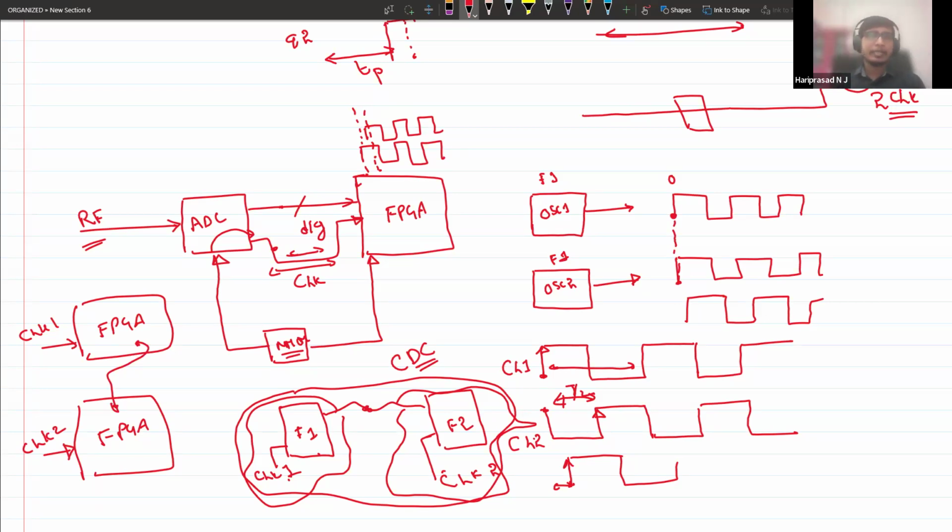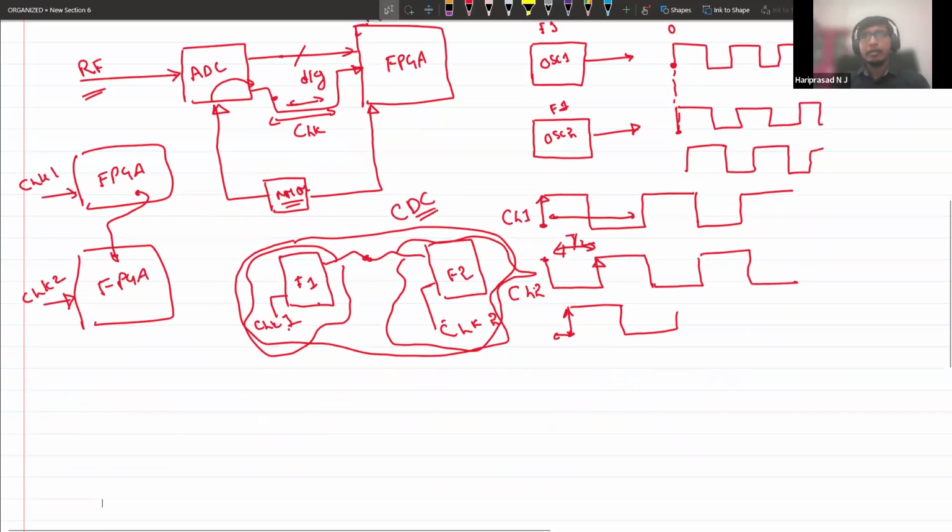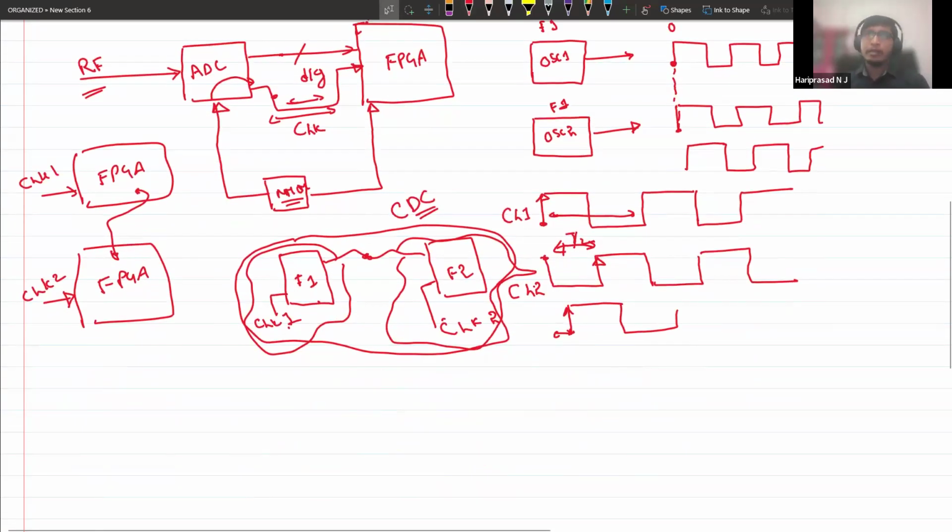Now, do you directly take this data at this particular clock? No, it will cause metastability. So how do I handle this? Any methodologies you have heard of in digital logic? The obvious methodology we follow is double clock synchronization. Double, triple, anything is possible, but as per MTBF analysis, especially in defense applications, we may go for more stages. Generally we go for double clock synchronization.